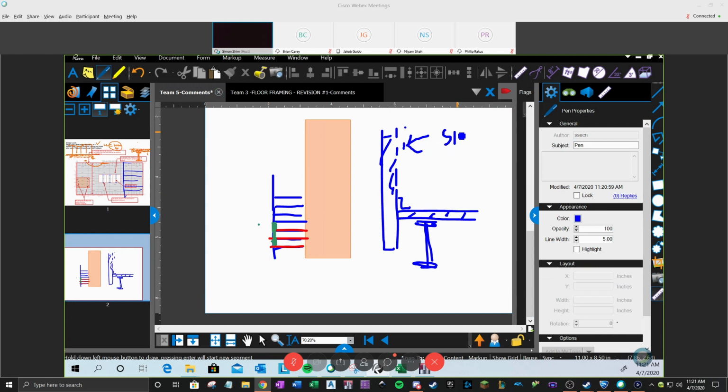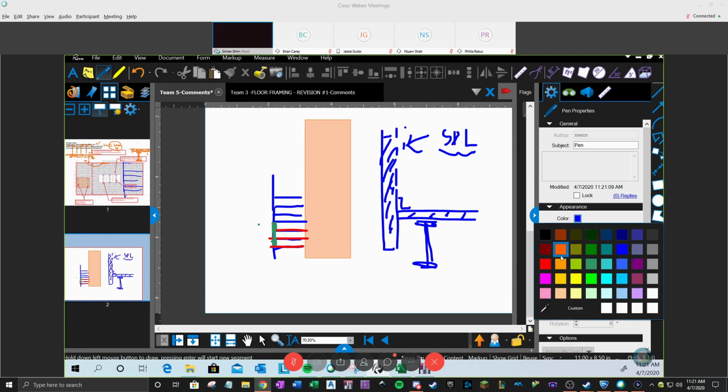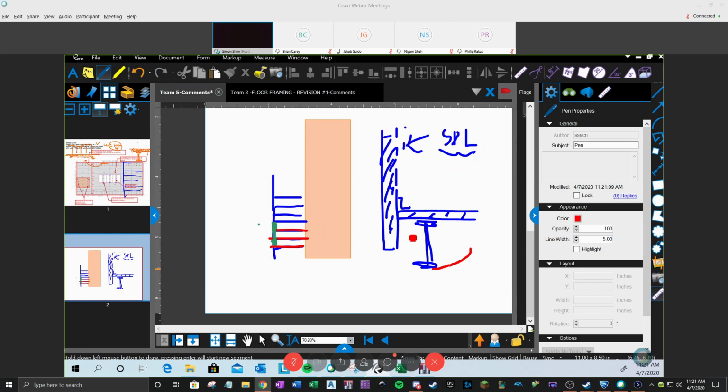It's not a structural element, right? Structural elements are limited to the steel and concrete slab. That's the structural element, so we treat it as dead load, self-weight of the structure. But curtain wall we treat as superimposed dead load.